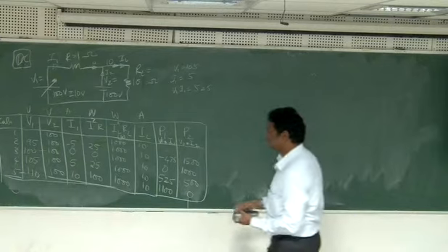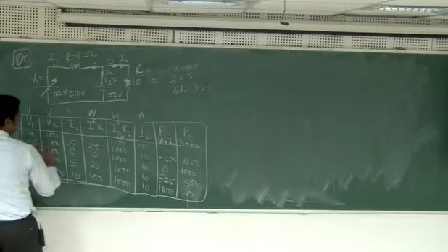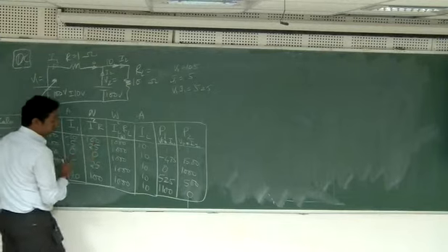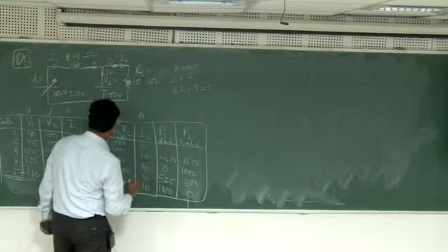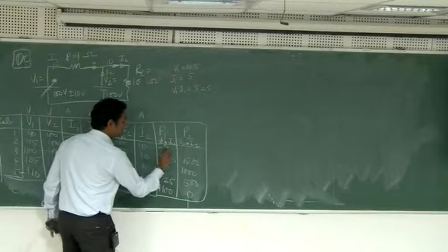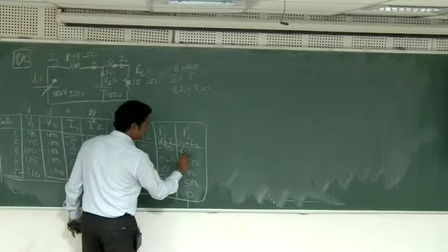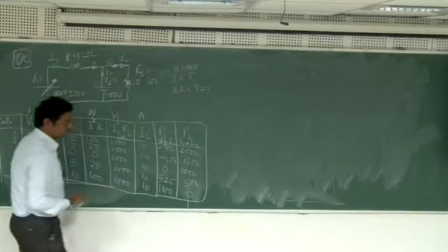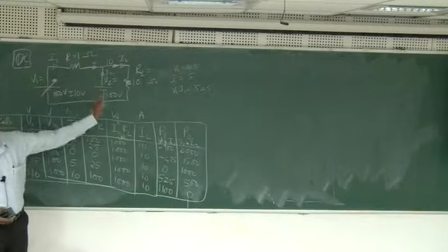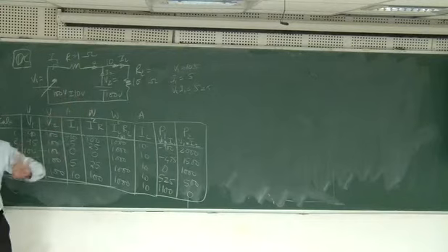Similarly, in this case, if the voltage was 90, then the current will be minus 10 amperes, and 100 watts will be lost, and V1 at 90 into this one will be minus 900, and this will be 2000 watts. Okay. So what do you understand from this? You can control the power flow between two places by controlling the voltage magnitude in the case of DC circuits.